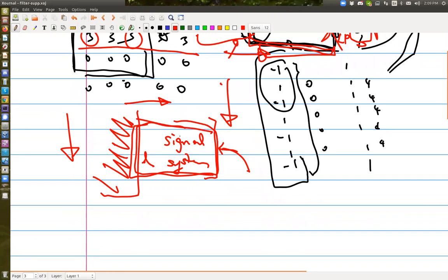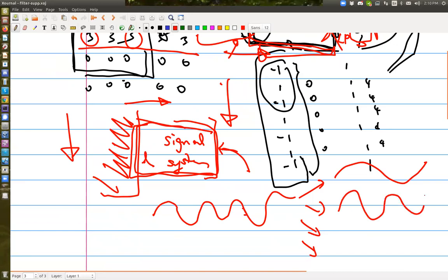In most actual applications, what you need to understand is that whether you have a 1D signal or a higher dimensional signal like 2D, you can always decompose the signal into different frequency components added together, as I drew earlier. A filter works on that: if I have a low pass filter, the lower frequency components get passed and the high frequency components don't.